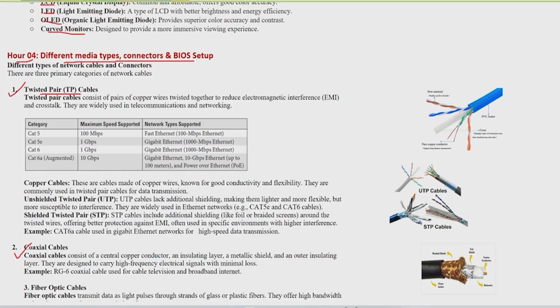See, a bigger one will trouble the smaller one. So those electrons will be forcefully going inside. That is why we say that whenever you are running network cables, avoid electricity cables nearby. If you run an electrical cable and a network cable in one duct, the data will have a very slow response and there will be problems in your communication.